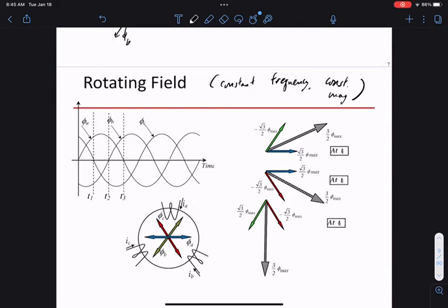Okay, so one thing you always have to keep in mind is that for an induction generator to work, somebody needs to give you this constant field. Somebody needs to give you this turning magnetic field. The generator does not provide it. The generator, or motor, responds to this, but something else has to give us a reference field that turns at some constant frequency.